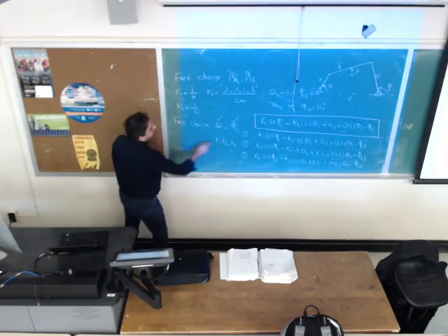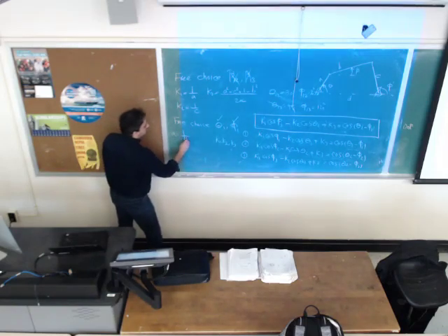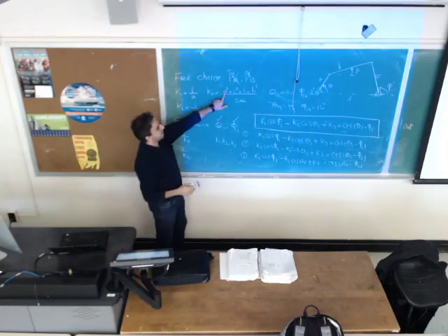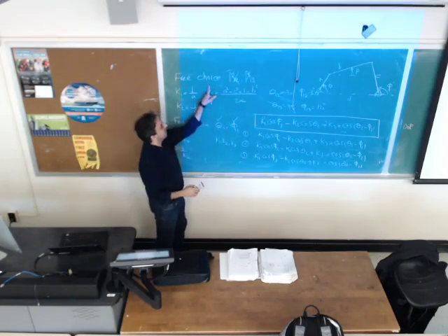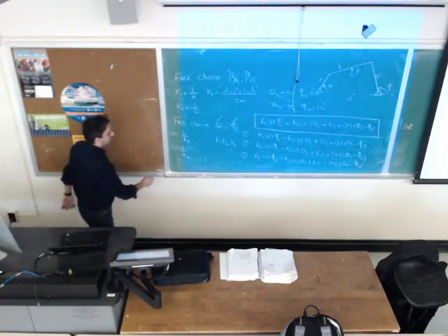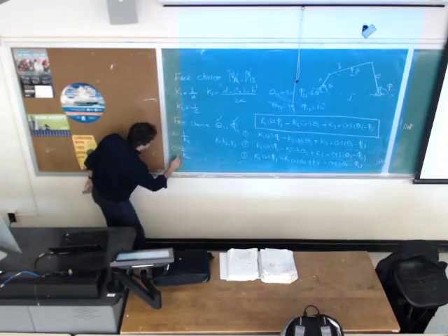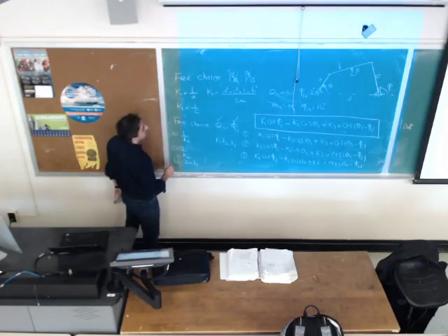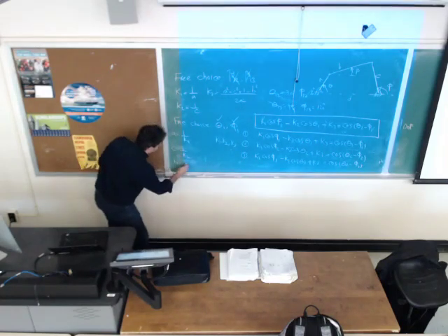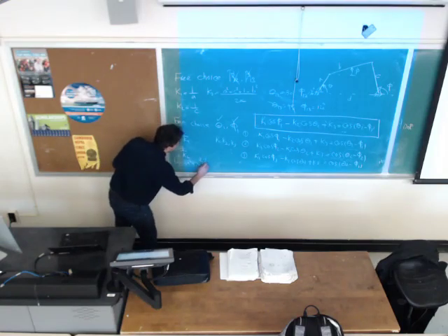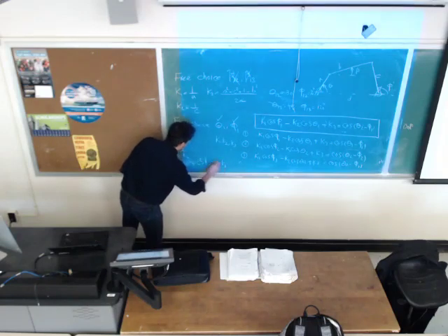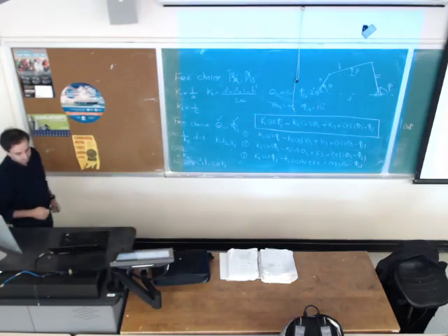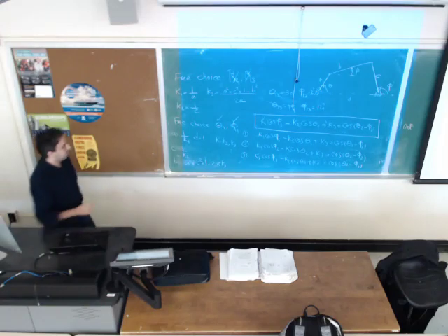After you find K1, K2, K3, A would be 1 over K1. C would be 1 over K2. You plug in A and C here, K3 is given, solve for B. B squared would be A squared plus C squared plus 1 minus 2AC K3. So you find A, B, C, and D is 1. So you are done with the design or synthesis of the mechanism.